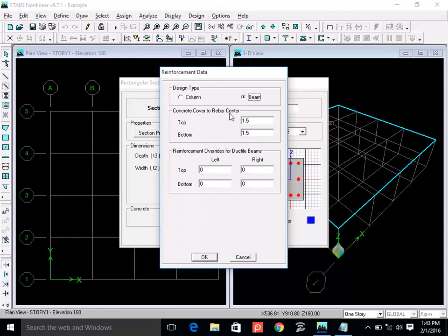Generally, we don't go beyond number 25 in the case of beams. So what you need to do here is review the sizes of steel bars, both SI and FPS.